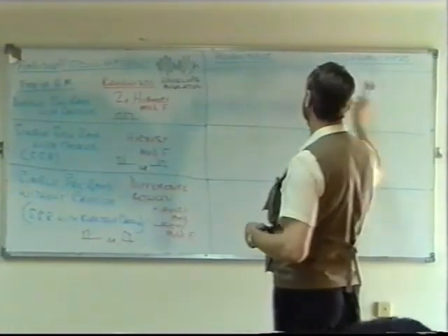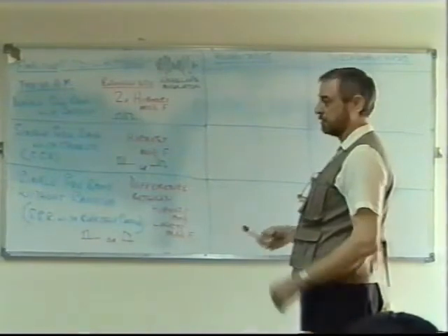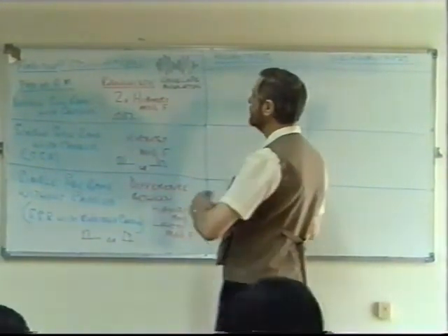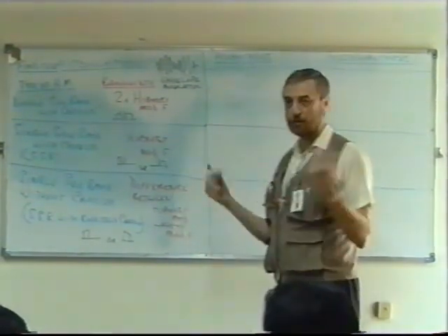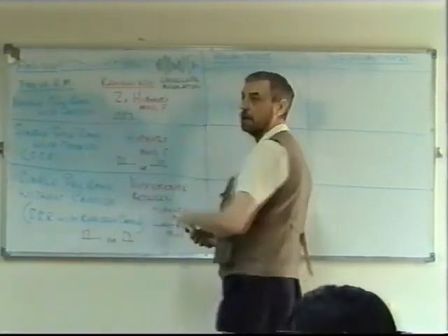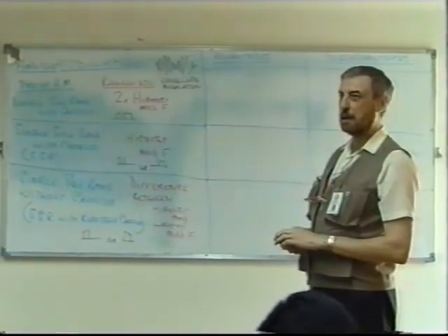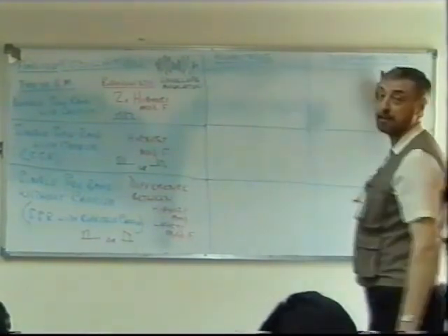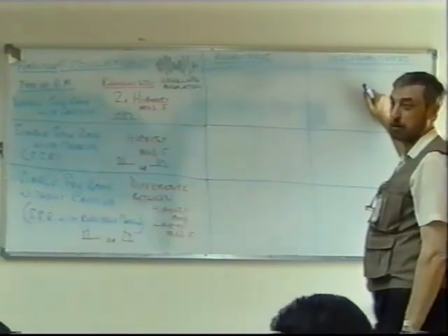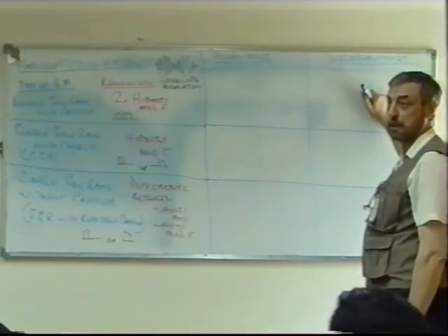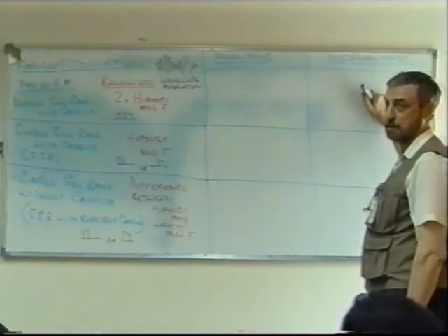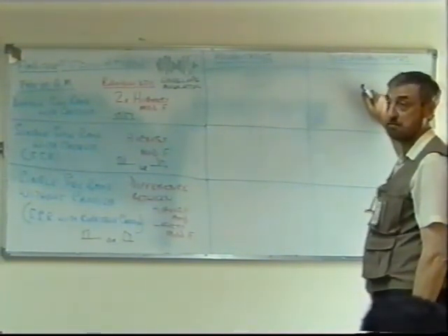Okay, let's have a look at the advantages and disadvantages of each of these three types of amplitude modulation. The first one, the advantage of using the basic 2 sidebands and 1 carrier. This is what's produced when we envelope modulate our signal. Can anybody think of any disadvantage in using that? High power almost. What about bandwidth? Wide bandwidth, yes. It's not as efficient on bandwidth, is it?